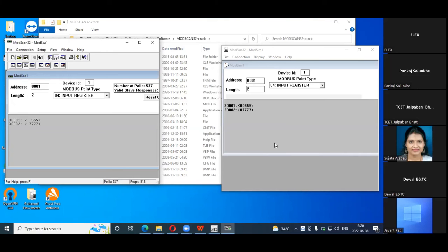And whenever that 400 degrees Celsius temperature is there, at that time it gives 20 milliamps output. So according to that, we can scale this particular temperature range. Now we are scaling that range, but the manufacturer, the temperature transmitter, stored that data in a register, maybe in a holding register or maybe in an input register.